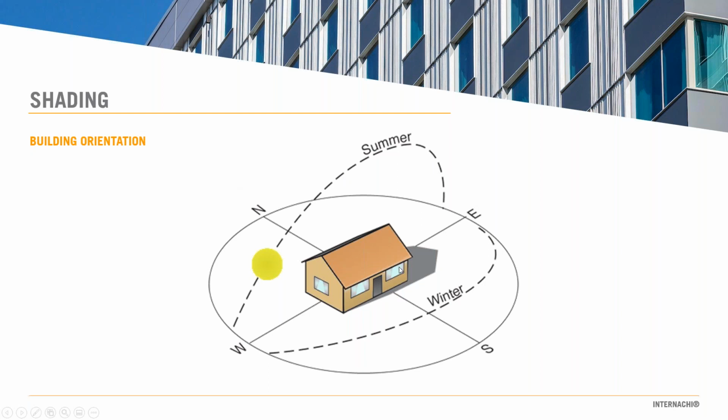The next key concept for your building envelope performance is shading. So you have a lot to optimize. The first thing is the orientation of the building. And this also plays into Passive House principles. We want to minimize the heat loss or unnecessary heat gains in the summer to avoid cooling loads, and also heat loss in the winter. And sometimes in Passive House, optimize heat gain to minimize heat loads in the winter time.